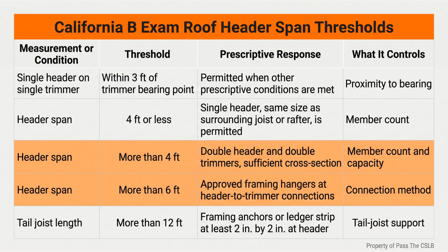A manufactured truss is a stop sign for improvisation. I do not authorize a cut because an opening appears to fit between webs. I use the approved truss or engineering detail. The field decision is to recognize the design boundary before structure, schedule, or inspection is put at risk.